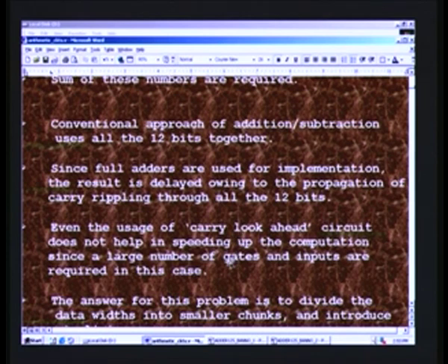If you test it when compared to a ripple carry of the same width, over an FPGA platform or an ASIC platform using Synopsys DC compiler, you will get a figure which is far less when compared to even the ordinary ripple carry, and that is the reason why this carry look ahead circuit does not really help.